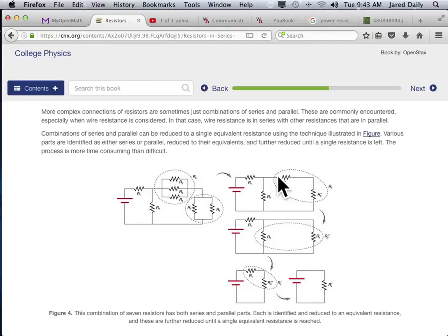And then since now these two are obviously in series, remember, you're in series if you go through one resistor and then go through the next resistor without anything in between, no branches in between, can't be a branch off in some direction, no elements in between. If they're just lined up one after the other with nothing in between except a wire, one single wire, no branching wires, then they are in series, right? Then you can add them together just simply, 1 ohm plus 5 ohms or whatever. And that makes a resistance in series that you can replace these two resistors with.